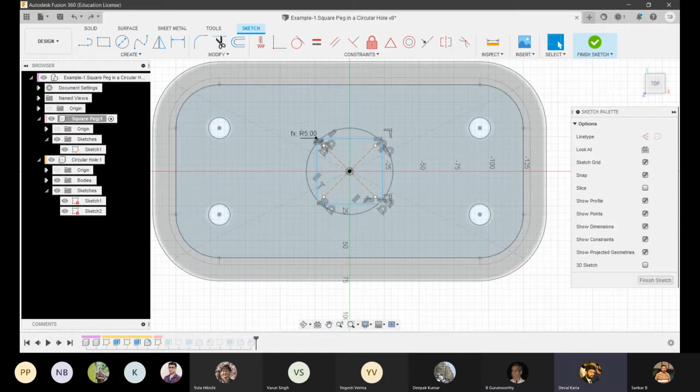So that is something you need to be careful about, because since you created so many dependencies on the original dimension, if the sketches are not constrained, they will not operate as you intended. So it's always good practice to make sure all your sketches are fully constrained. That way, you know that the sketch will only change as you want it to change, right?